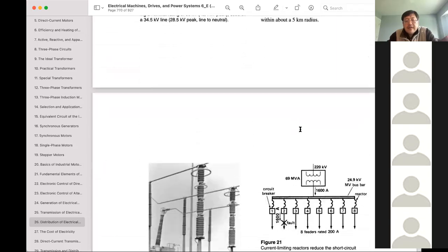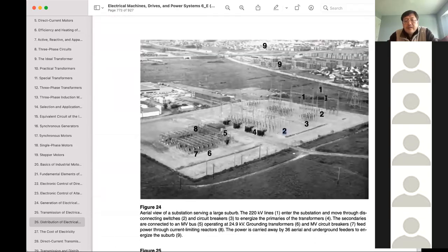So on the substation, you have switches. Right in between the switches, you have circuit breakers. After the switches and circuit breakers, number 4 is transformers. 1, 2, 3. You have number 4 as backup. Generally, only 3 are needed for 3-phase, but they put an extra one just in case one of them blows up, and you can quickly rewire to the backup transformer.